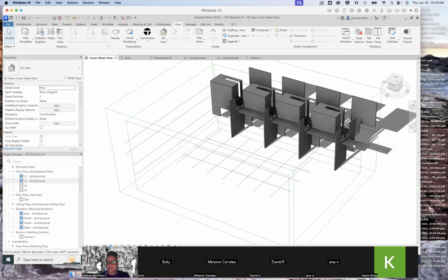Oftentimes you do that by trying to bounce direct light from the outside into the inside, right? So horizontal louvers, shades, brise soleils, breeze block, all those sorts of strategies that you see throughout over centuries and millennia in the deserts and other hot environments. Those are there for a reason, right? Because they're trying to screen light from heat.